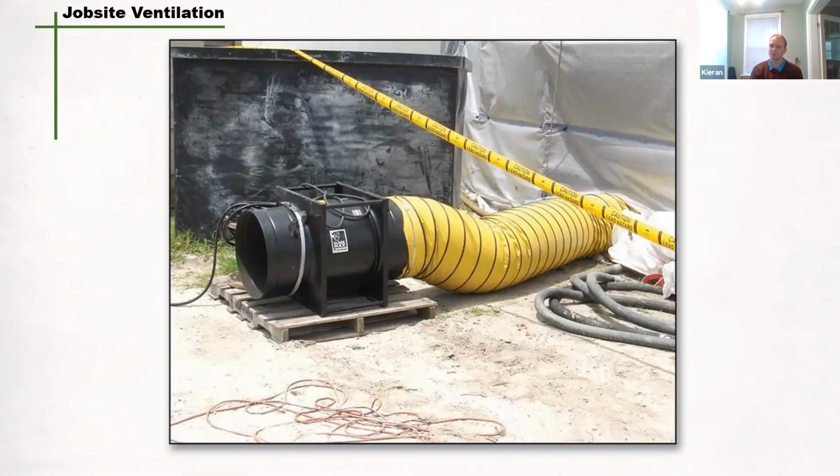So in a higher risk situation, such as a hazardous confined space, companies may create some sort of fume and you are required to ventilate. If you can't ventilate, that's when you have to don atmosphere supplying respirators or SCBAs. So sometimes the best situation is to use ventilation.